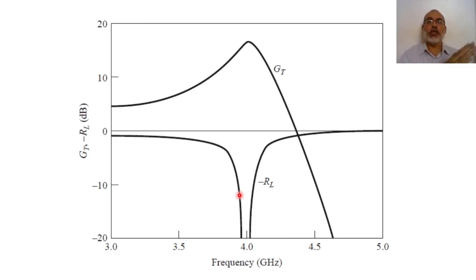But just outside the operating frequency, this gain will drop dramatically. That's why if we are interested in designing a broadband amplifier, we should not design this amplifier at the maximum gain. We should reduce the gain slightly to make this gain broadband, and at the same time the reflection coefficient would be matched over a slightly wider band.